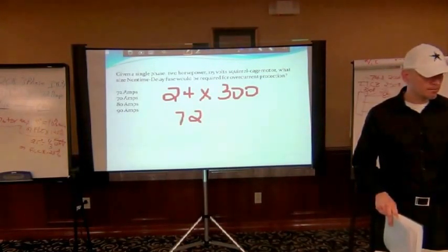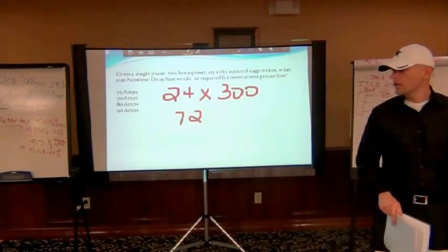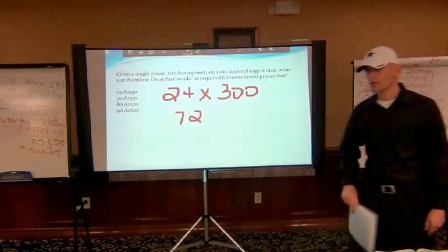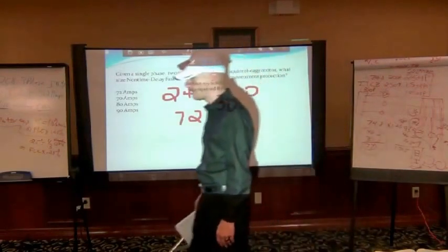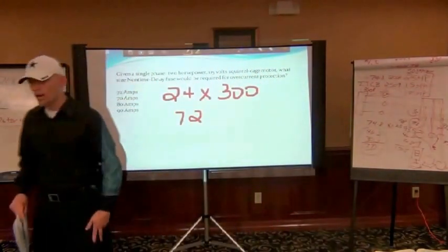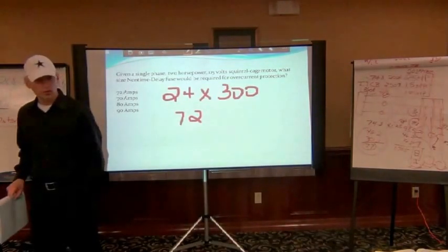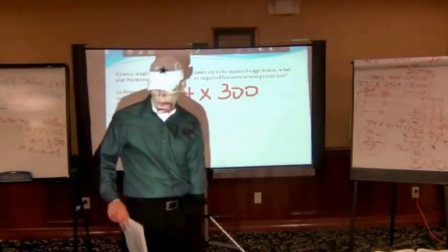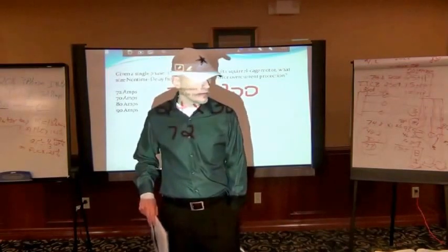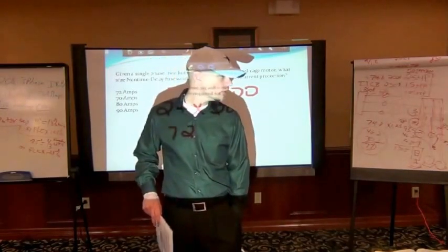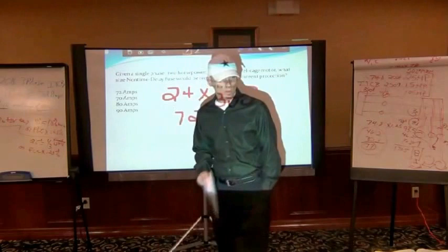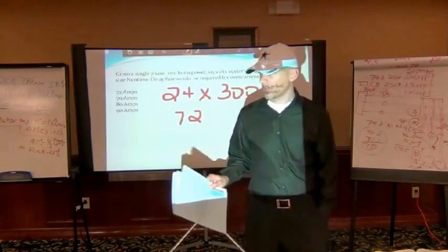Where'd you get 115%? On what page? Now remember, we have a table with a different duty rating than continuous duty. We have a table that's under 430.22(E), right? Page 317. So here wire does have something to do with this table.